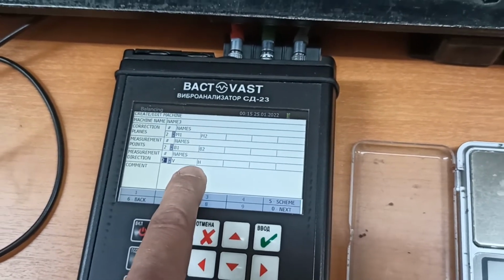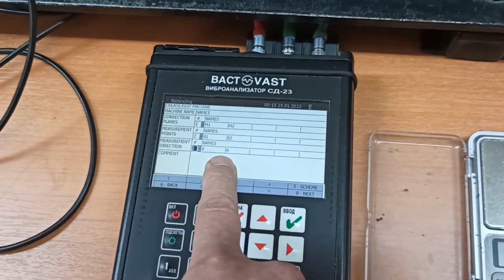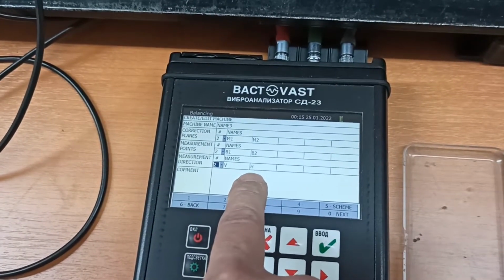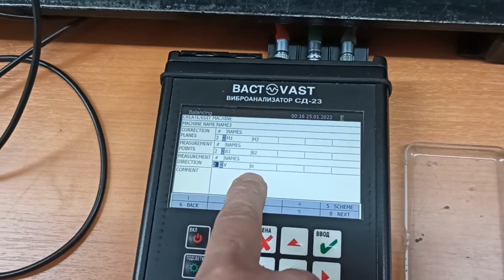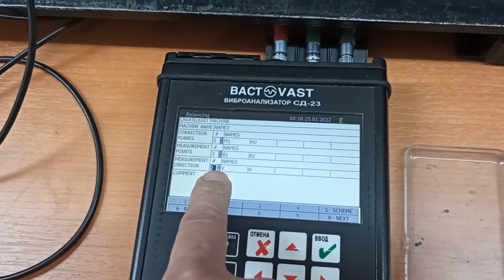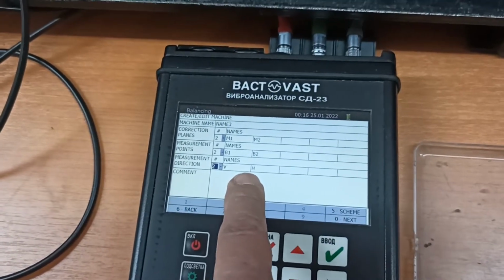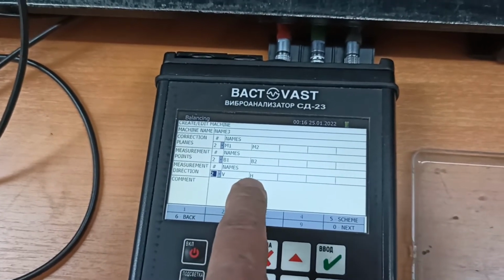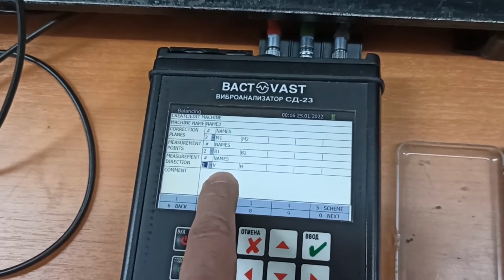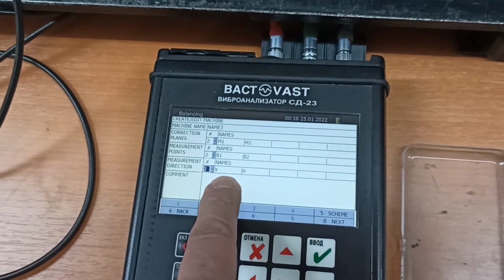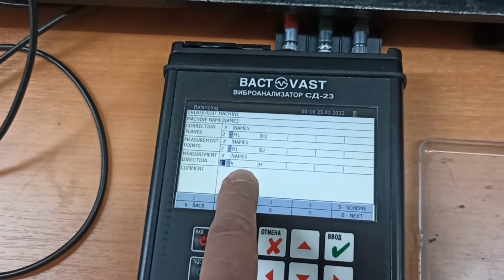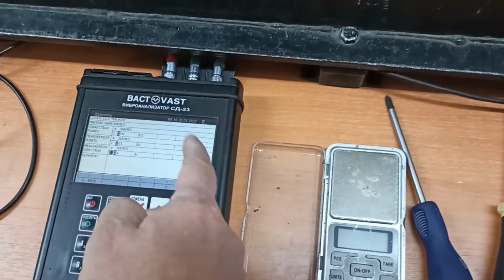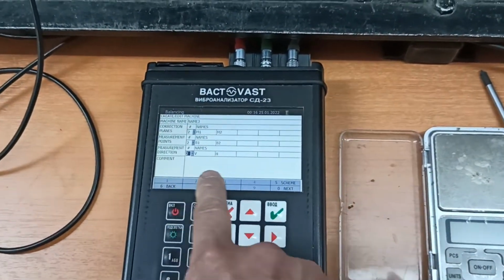Why is it needed? It is needed because you may have different stiffness or rigidity of your support structure. So if we decrease vibration in vertical, we should monitor that it will not increase in horizontal. Also, if you have very different vibration levels in 2 directions, then you may have a problem like a resonance. So this is the required setup of the machine.